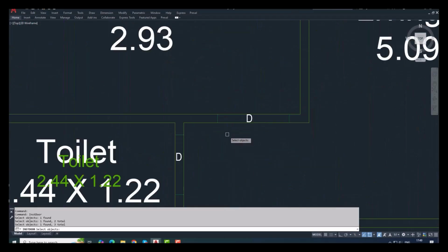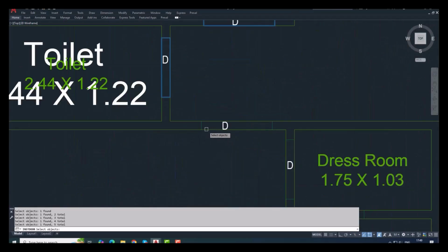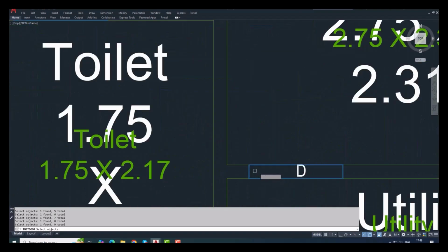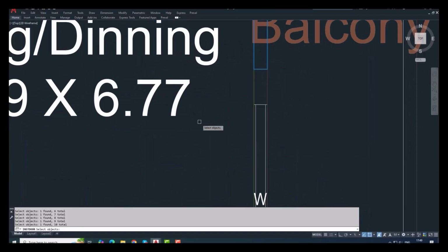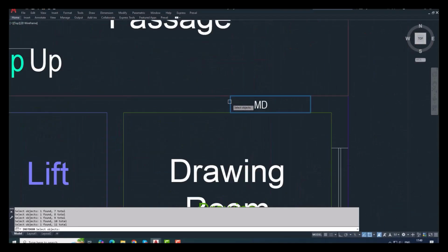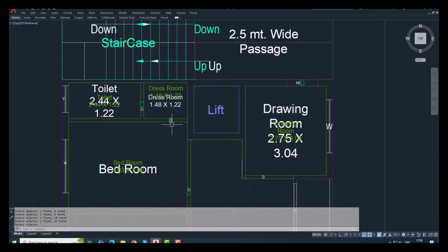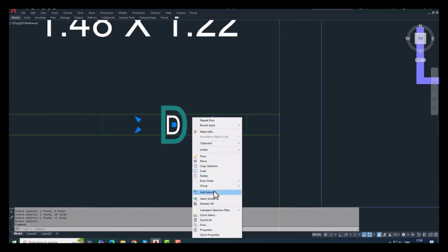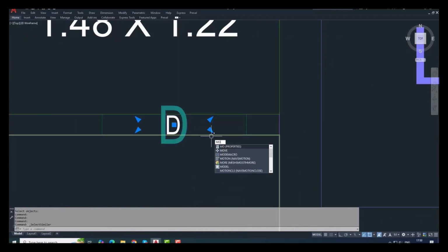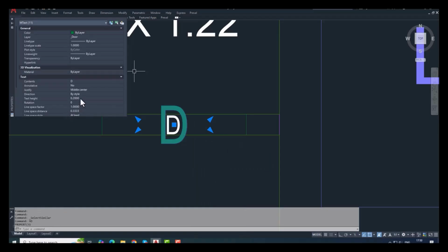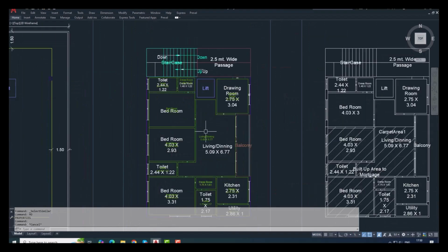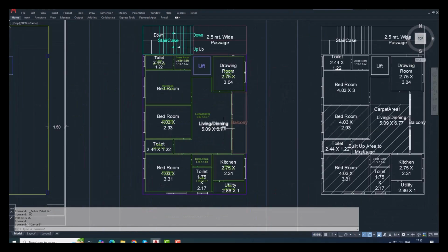We have the option for multiple selection of door labels. We can also change the name variably according to the desired door. Now we selected 11 doors and we pressed OK to get the labels of the doors. We have to make sure that all the labels have the properties matched, and we reduce the size and scale of it to have the text comfortably inside the desired polygon.